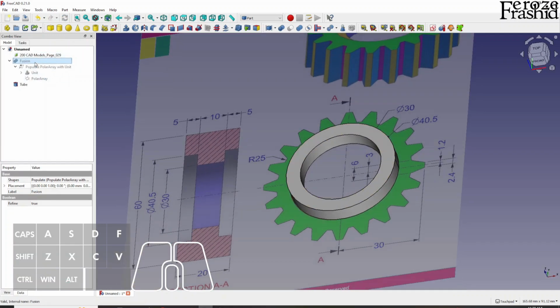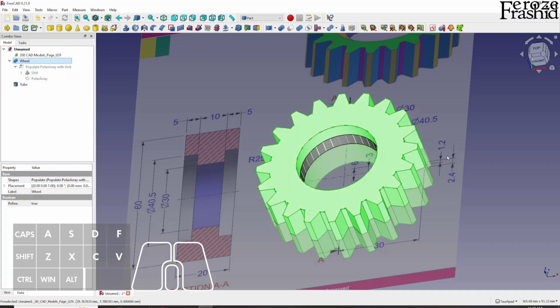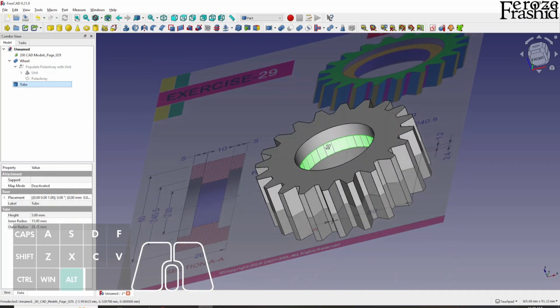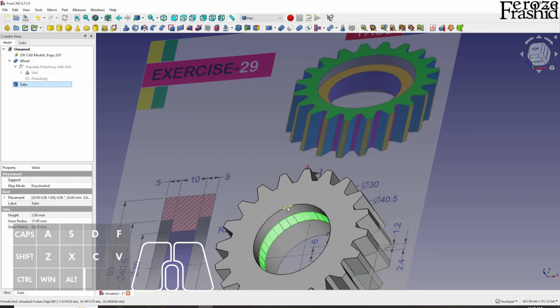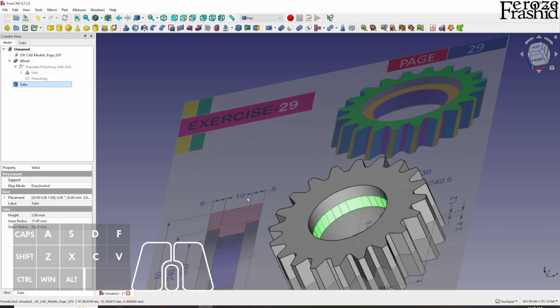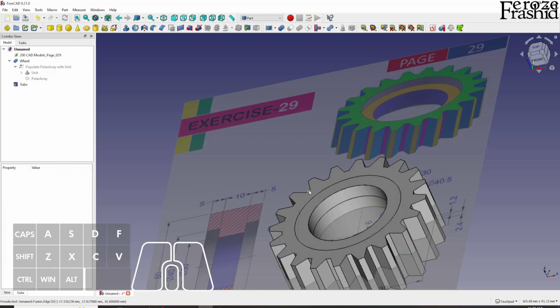Let's bring our fusion or the wheel back. Let me actually rename that. Say wheel. Cool. Now, do you see what the problem is? This tube is not where we wanted it to be. This wheel should be at this level, and it's at the center now. So we can fix that. We see the gap between two sides is 10, so the midpoint is 5. What I have to do is take the tube, place it at z direction 5. That way it moves up to the level, right?